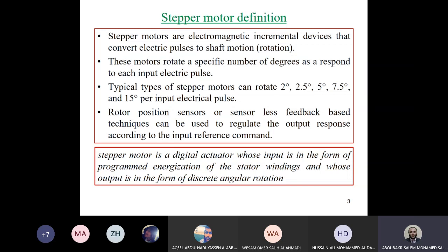So if the machine is stopped at a certain angle, which means the electrical torque of the machine equals 0 because the machine is not working, this will not allow the cartridge to print the line in the proper way because the paper will not be fixed. So we need the motor to fix the machine, which means we need a motor that has holding torque.